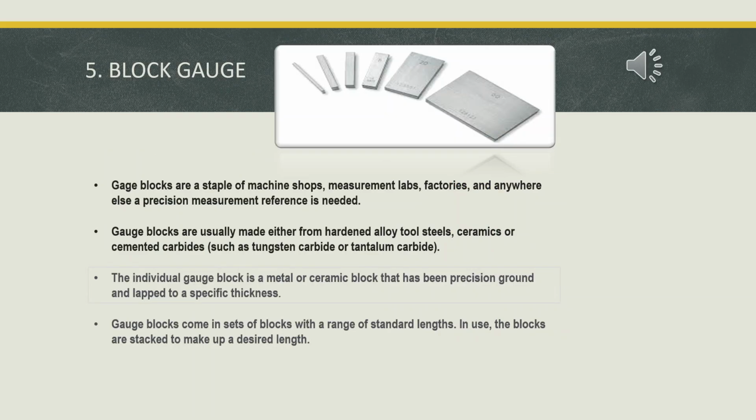Hi, my name is Aaron J. Salvador and I will explain what a gauge block is. A gauge block is a block of metal or ceramic with two opposing faces ground precisely flat and parallel, a precise distance apart. An important feature of gauge blocks is that they can be joined together with very little dimensional uncertainty. Gauge blocks are the main means of length standardization used by industry.